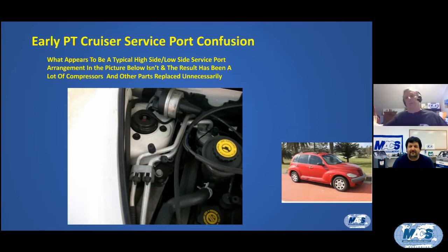Now, I realize that we're talking about vehicles here that are 18, 19 years old or so, but there were tons of them sold and they're still out there. So right here, it says, what appears to be a typical high side, low side service port arrangement in the picture below isn't, and the result has been a lot of compressors and other parts replaced unnecessarily. So, here we've got two service ports side by side.